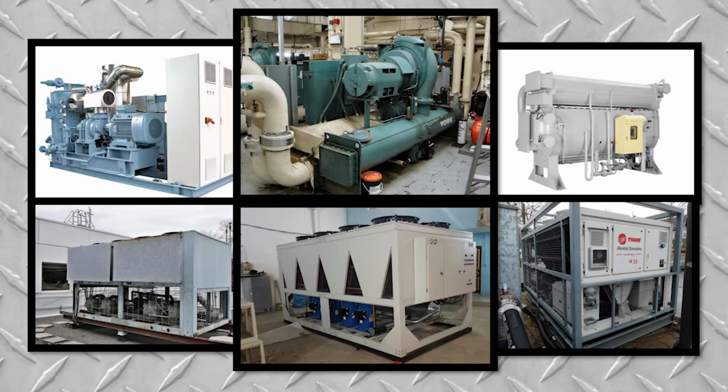So to mitigate the effects of offload performance, we propose the idea of having multiple chillers, but having them of different sizes. According to industry surveys, about 80% of industrial plants with chilled water systems have more than one chiller. So they understand how to do that. That's the good news. But the bad news is if you don't run them correctly, you may not be able to help anything.